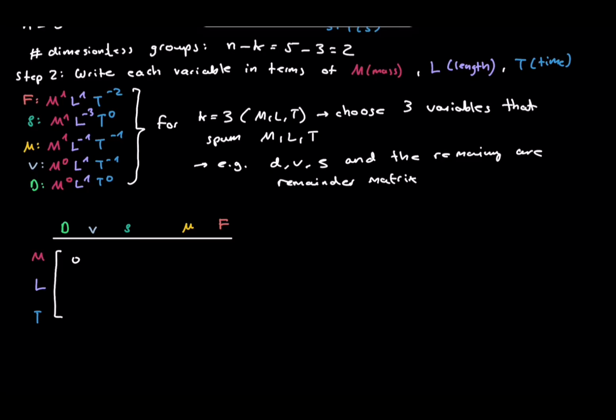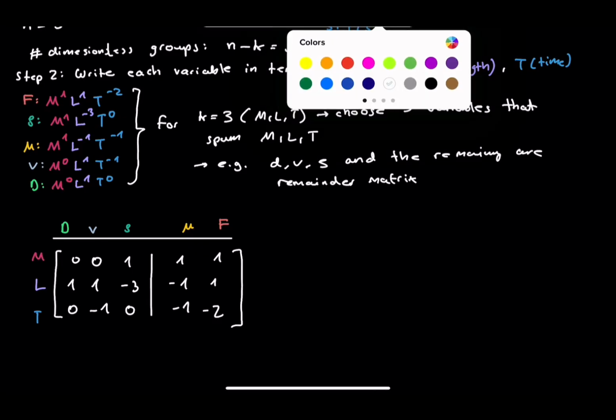You can choose different repeating variables, but a good choice makes the physics appear naturally. Here we choose density, velocity, and diameter, because this choice leads directly to the Reynolds number, which is used constantly in fluid dynamics. Now comes the key idea.